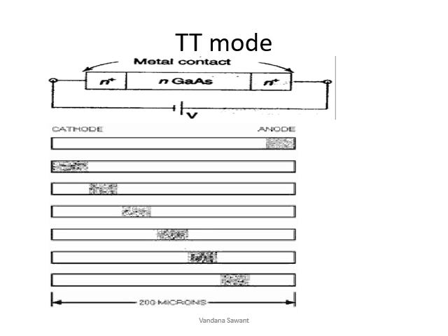This bunch of electrons has a slow or lower mobility, and as these are negatively charged particles, they will try to move towards the anode. As the mobility of this bunch is decreased, it will take some time to reach the anode, and the time taken by this bunch of electrons from cathode to anode is called the transit time.